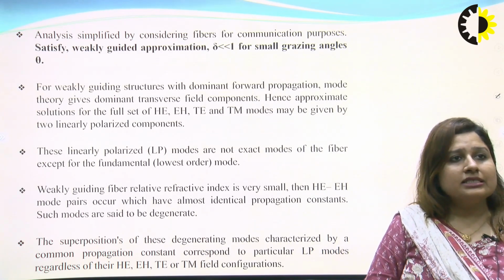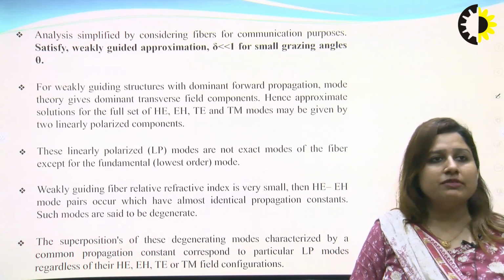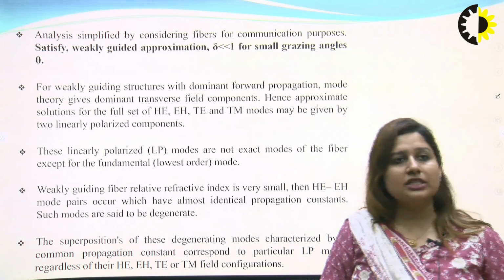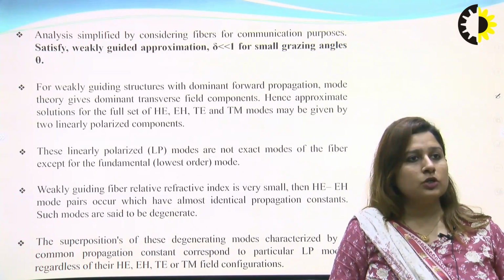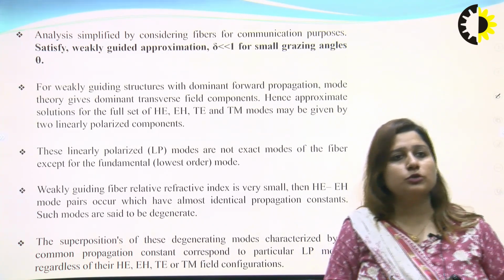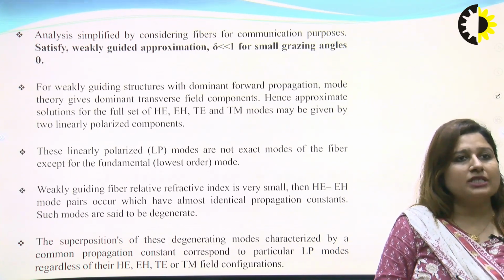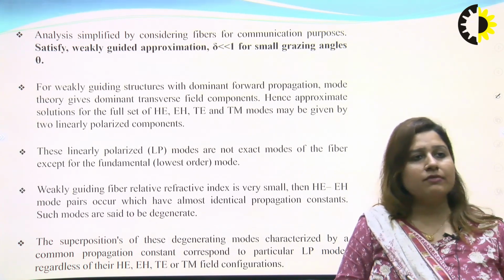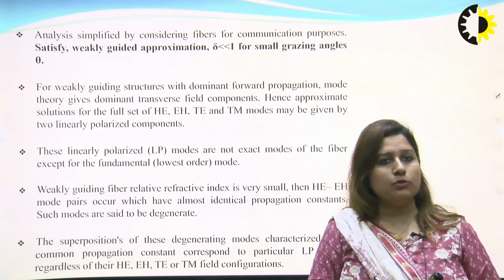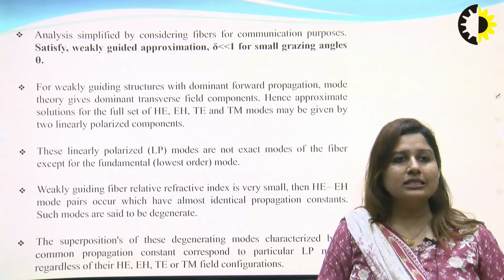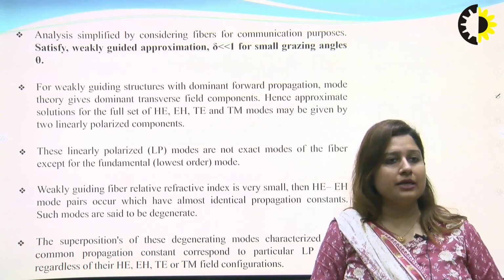So, analysis is simplified by considering fibers for communication purposes. Here we satisfy the weakly guided approximation, that is delta is very much less than 1, for small grazing angles theta. So, for weakly guiding structures with dominant forward propagation, mode theory gives dominant transverse field components. Here we have full sets of HE, EH, TE and TM modes. So, there are 4 modes here as compared to TE or TM modes in the case of the planar waveguides.